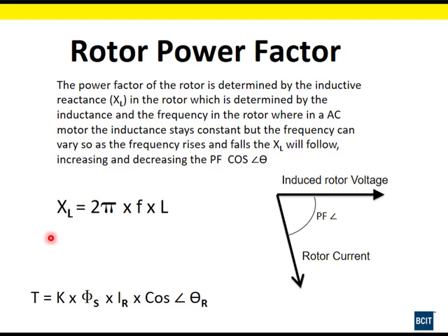Now, all the way up to full speed, where it got down to 1.6 hertz. That 1.6 and that change in frequency will have a significant effect on our rotor power factor. If we look down here at our original formula, we can look at the strength of the stator field, the current in the rotor field, but here's that power factor of the rotor we're going to look at.